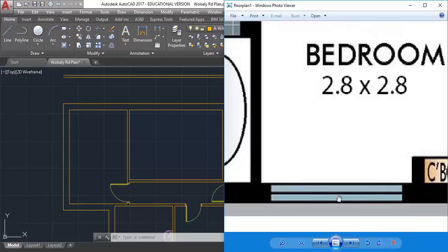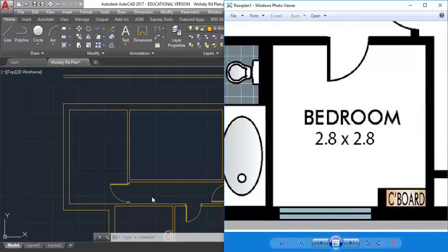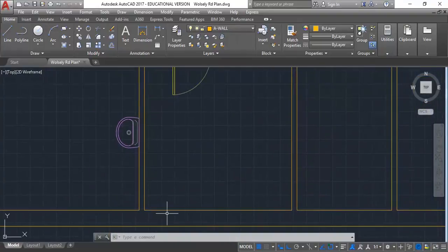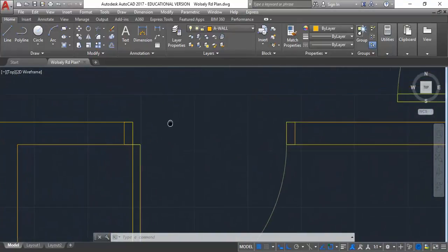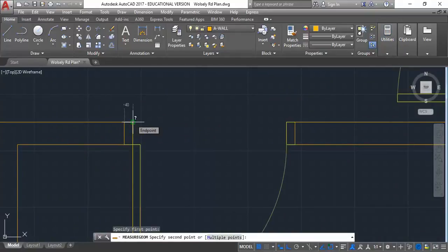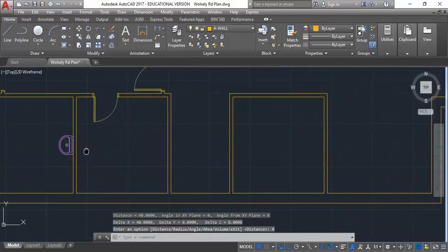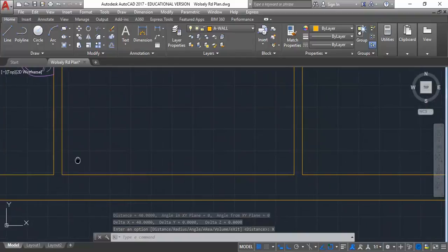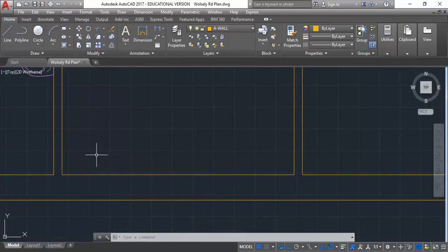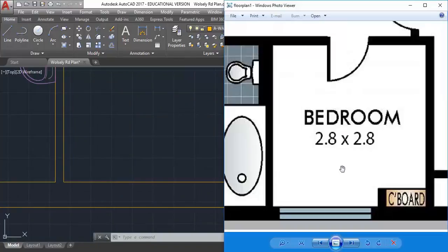If you're drawing them in a basic sort of diagrammatic way, like you can see this one is here. So you might remember with doors, the convention is to draw the door jambs 40mm across. With windows, the convention is that you make them 50mm. So as long as you know that, and then also the width of the window, you shouldn't have any problem drawing them.